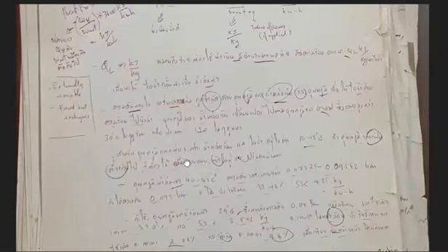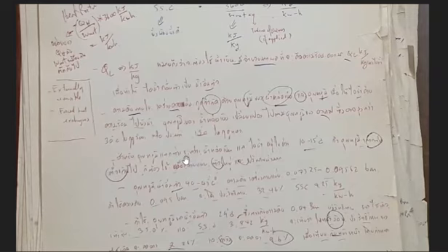This just tells the benefits of doing that. Mainly, the goal would be to increase the high temperature TH and to decrease the low temperature TL. Another thing that we want to do is to reduce the amount of water droplets in the system, because the water droplets are harmful to the turbine and can cause corrosion.